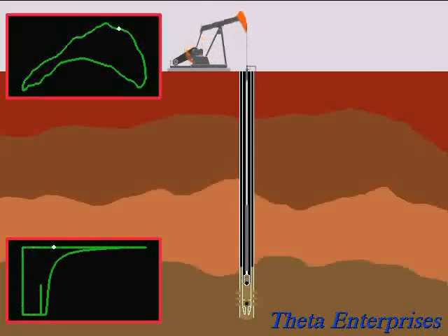In this case, for example, we have fiberglass and steel rods with sinker bars on the bottom. When that compressive wave goes through the sinker bars and hits the interface between the sinker bars and the fiberglass rods, because of the large change in diameter and material, a lot of that energy gets bounced off and goes back down. When it reaches the plunger, it makes the plunger temporarily pause or stop, and then it starts to pick up the fluid load, and then it moves again and releases the fluid load.